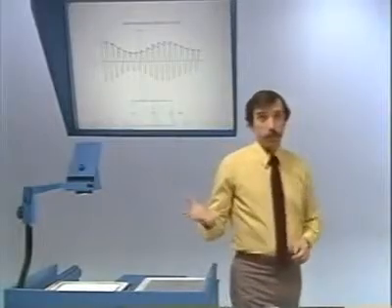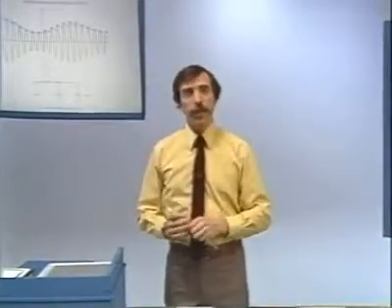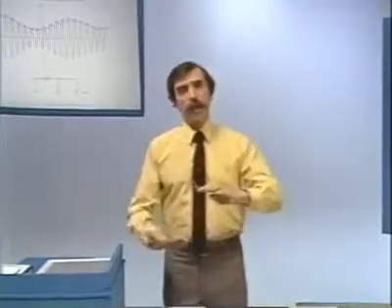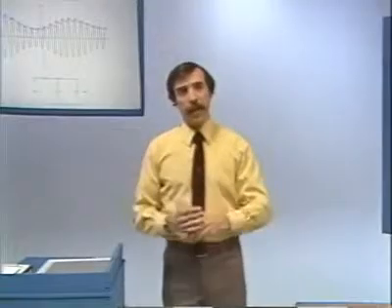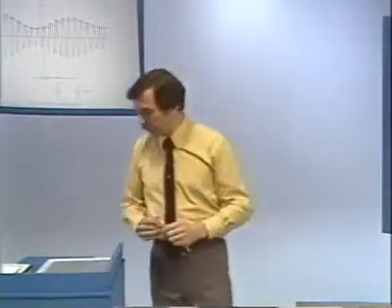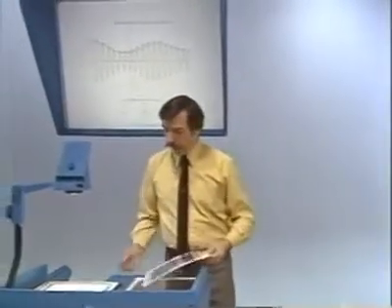Now, there's a simple solution to this. The simple solution is to make sure that the modulating signal, x of t, never goes negative. A voice signal tends to go negative, so if it happens to, we can simply add a constant to it, and add a large enough constant so that it always stays positive. Well, let's look at that.